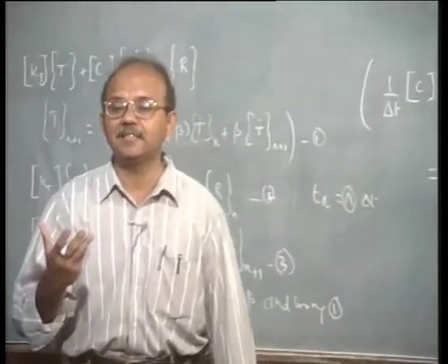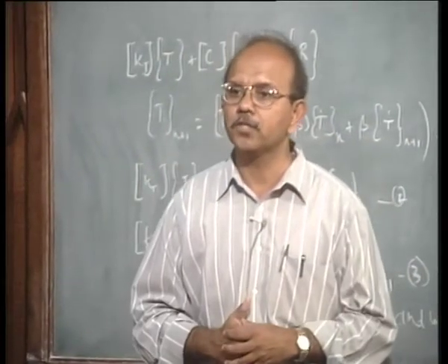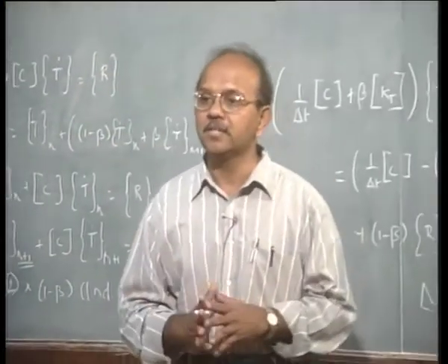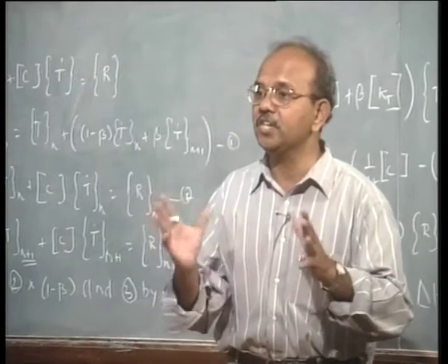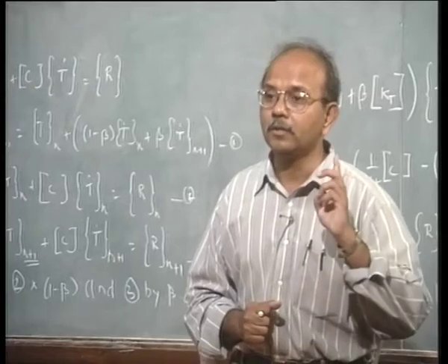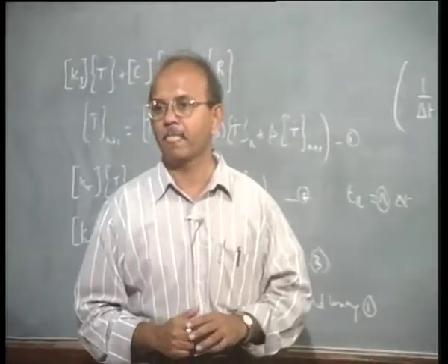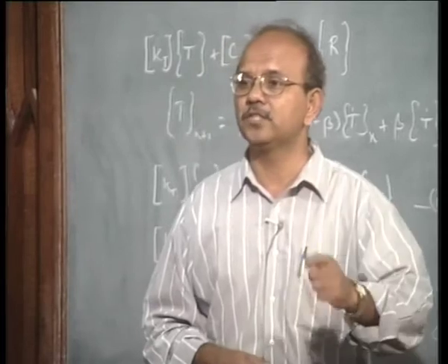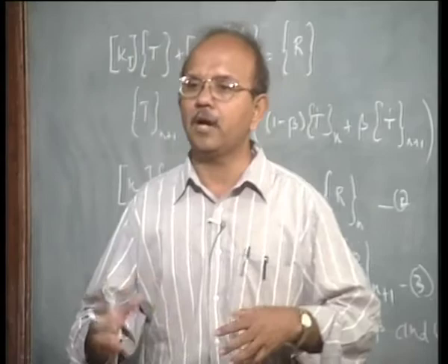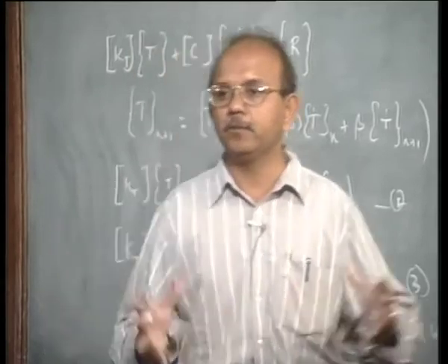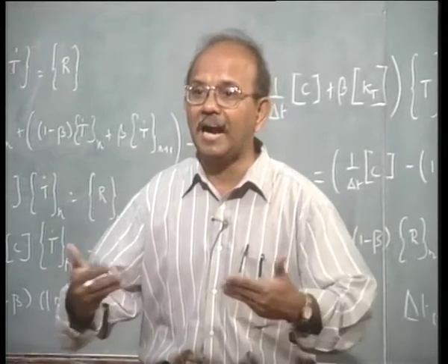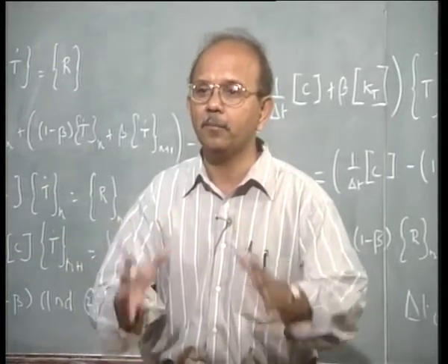The coefficient of thermal expansion and the temperature gradients result in an initial strain epsilon 0, and that is what we are going to handle. So the loading is through these initial strains. But if you have any other type of loading, maybe you weld under pressure or something like that, then that also has to be added to the loading condition for the mechanics problem.